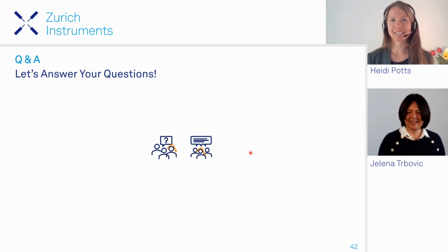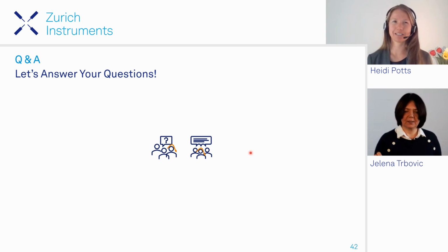Yeah, absolutely. You can sweep the DC bias voltage. I've quickly shown that we can generate a test signal that consists of a DC voltage component and an AC component. The way this is done is that you create a DC voltage with the MFLI that is then added on top of your modulated signal, and then you can just sweep this DC bias voltage as you wish. You could use the sweeper to do this, for example. And obviously this is required if you want to map out these Coulomb diamond diagrams where you have the DC bias on the y-axis.